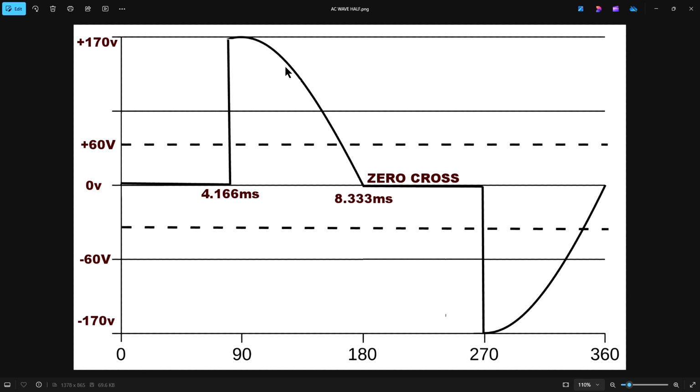It's just less power, not necessarily less voltage, not necessarily less current, just half of the cycle. So the area under here is half the power. So the light dims. This is how we create light controllers for everything. We dim lights doing this.